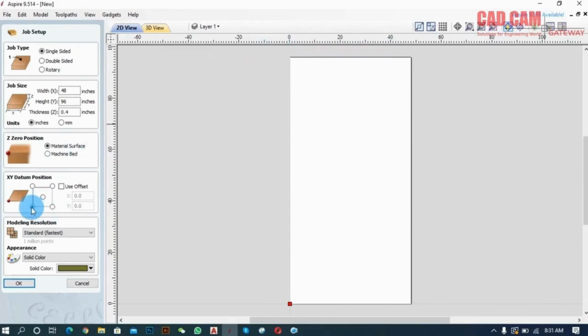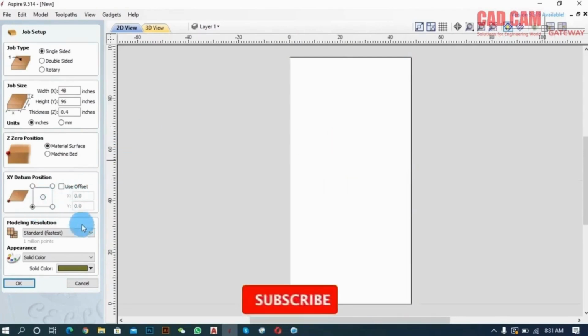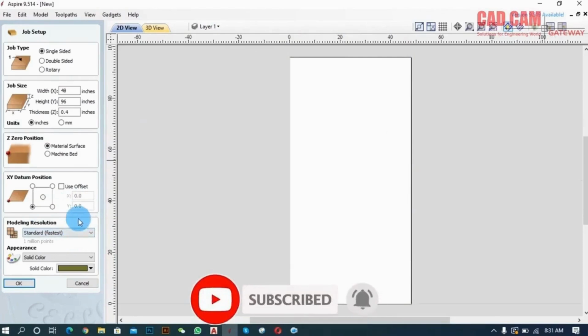The normal practice is here. Often what we do is when there's a small piece, we take its position in the middle. Meaning if, let's say, you have to work within a foot or two, instead of managing the margins and other things on the sides of the design, which becomes a bit difficult, the best way is to cross it from here to here and from here to here, mark its center point and set your tool's home position at its center. Then, whatever designing is done, it will automatically leave equal margins on the sides. So you don't have to keep setting their margins yourself. This is also a good practice. So I will now set its position here.